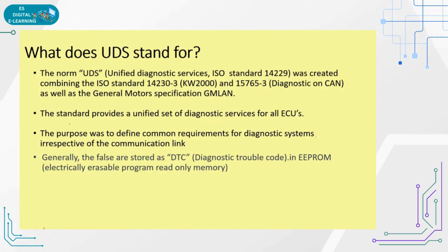You can write down notes on this point. This is a very important point you need to remember. Underline this: faults are stored as a DTC, diagnostic trouble code, in EEPROM memory. The full form of EEPROM is electrically erasable programmable read-only memory.